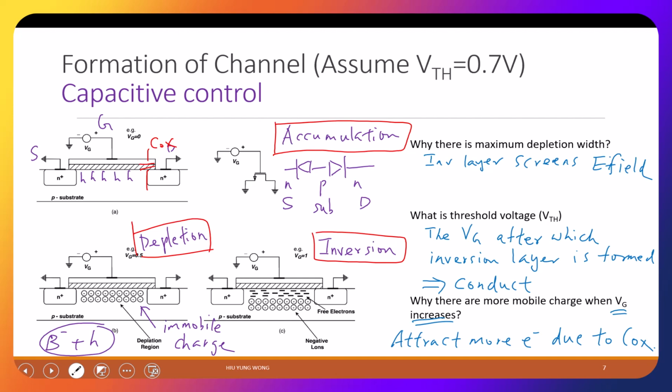If you forget everything else, you do need to remember what a transistor is. It is a transfer resistor. You use the gate to control the conductivity. Think about it, this is just a resistor from left to right, but its resistivity is controlled by this third terminal. That is the main point. It's a 3-terminal or 4-terminal, but basically a 3-terminal device. I use this one to control the conductivity of the channel, and then I form a transistor. Okay, this you must know, right? Otherwise, in the interview, how can you go through?